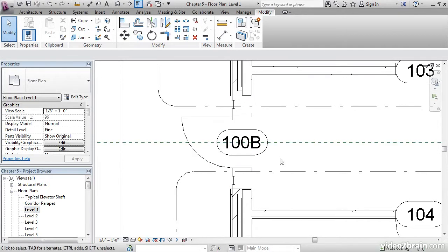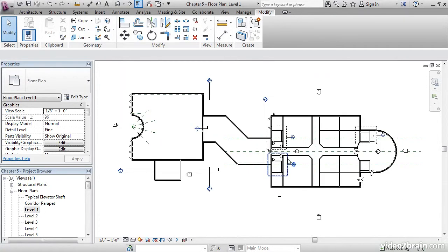While still in level 1, type ZA to zoom all. Save your model. You gotta love the Align tool. With the tools under our belts, we were able to add a window in a casual manner, align it to a good reference, then array the windows to form a cool little bay. We were also able to align and lock a couple doors to a reference plane.